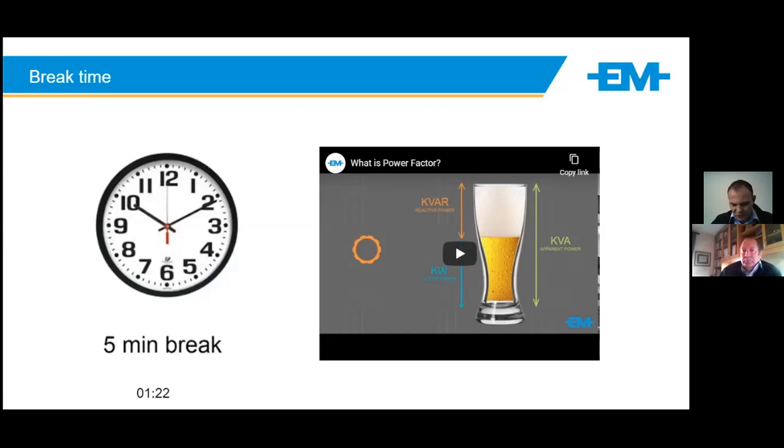All right, so the harmonic level is dependent on a few things. If you took an example, a 1 MVA transformer, and someone told you, oh, you've got a 10% THDI, the question would be, at that 10% THDI, what was the current or the percentage of the load of the transformer?